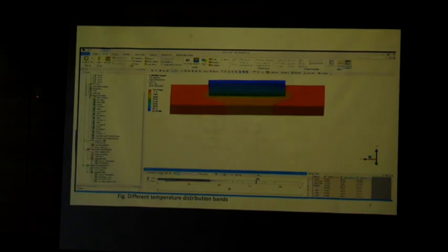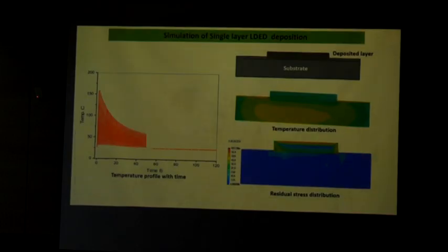If you see, these are all the data we have got. What we are getting here is temperature versus time. With respect to time, how solidification takes place, that is what the cooling curves mean. At 0 seconds, the temperature is almost 1500, multiplied by 10, so 1500 degrees centigrade.